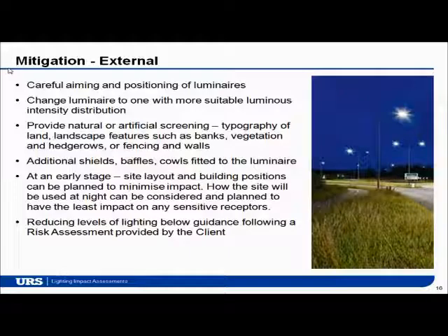Additional shields and baffles, cowls, etc. have been mentioned. This is something that we try to use really as a last resort because of some of the things mentioned about post-installation, whether they're going to be fitted correctly. But as we go forward and there are tests on site post-installation, I think this will be more of an option as well. But also, I think technologies sometimes mean that they're not needed. If we're involved at an early stage, we can also impact on the site layout. Another option is to reduce the lighting levels below that of the guidance, and to do this we usually liaise with the client and they produce a risk assessment to allow these levels to be reduced.